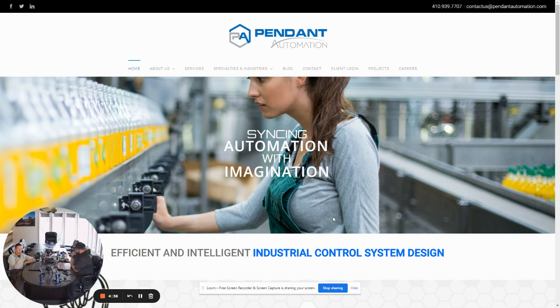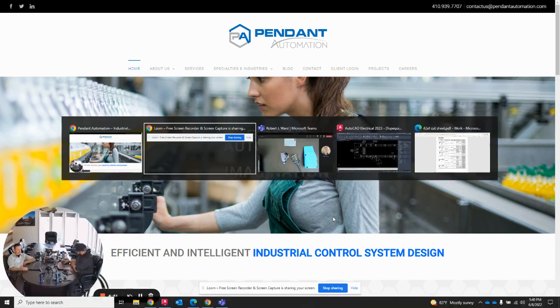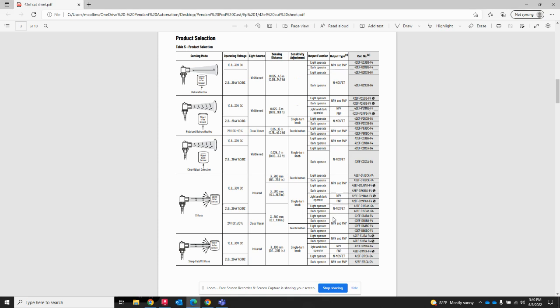So actually, I want you to bring that up when we talk about mounting, because the mounting is critical in photo eye placement. For instance, that photo eye at your garage door is always mounted about 6 inches off the floor. And technically, if you had half of your car in the garage and half of it out, it would still shoot underneath your car. Yep, and you could essentially still close the garage door right on your car.